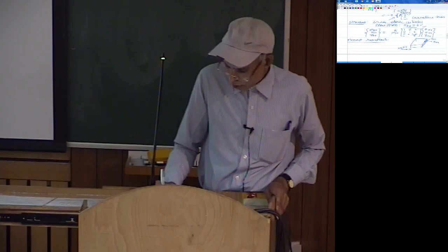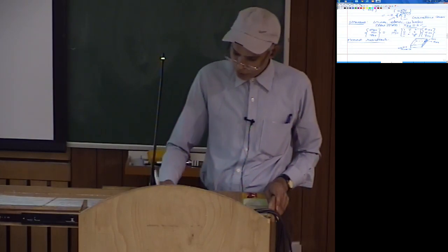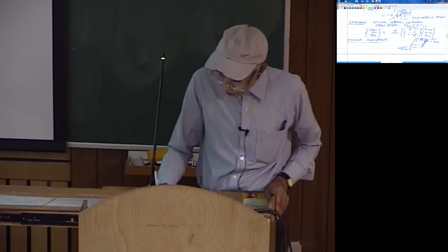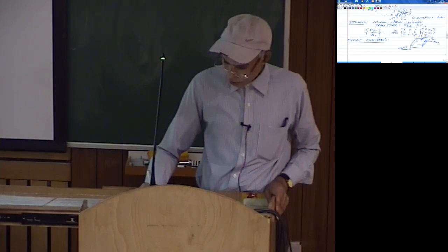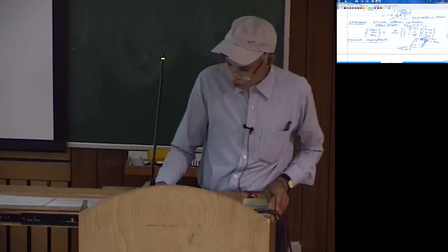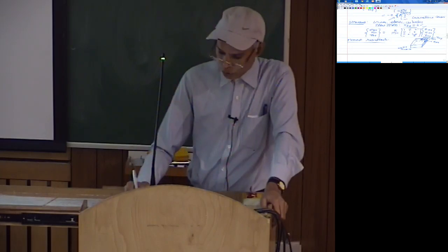Then if you look at the positive y face, again from the middle surface, for any small area on the positive z side here, you will have stress sigma yy, that is the normal stress, and you will have stress tau xy here, which you can say is tau yx, equal to tau xy. So these are the stresses.